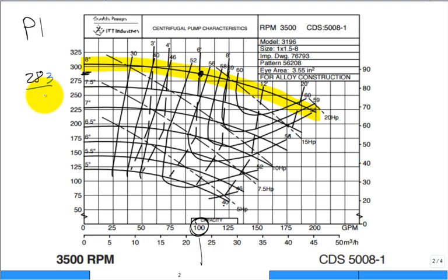But you could do it much more accurately, and you would find the flow through pump 1. Somebody want to just run a number on it? I'm going to pause. I want you to do it. All right, so for pump 1, the GPM, I came in right at 109 GPM. If you like that, give me a thumbs up. Very good.